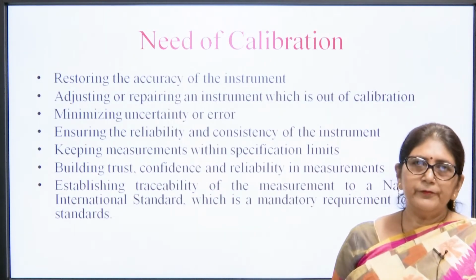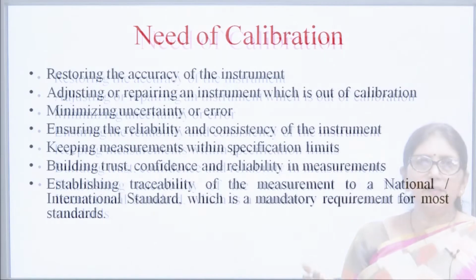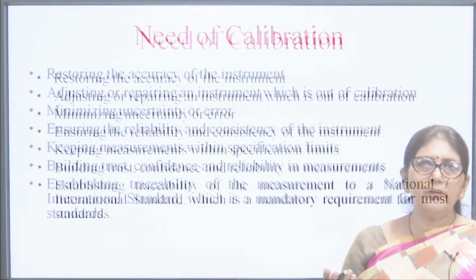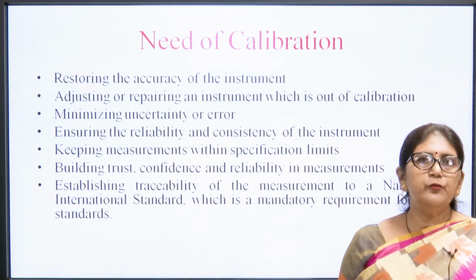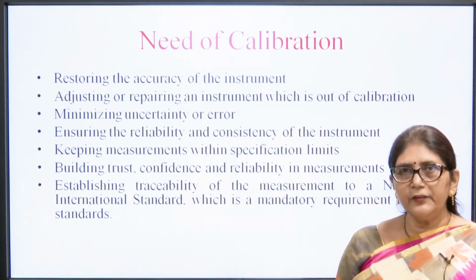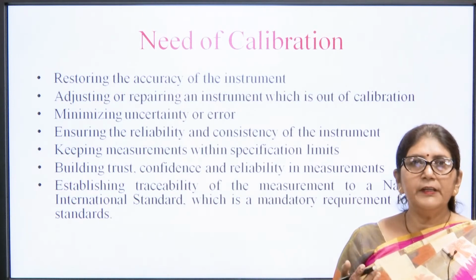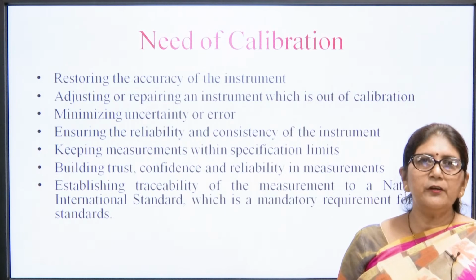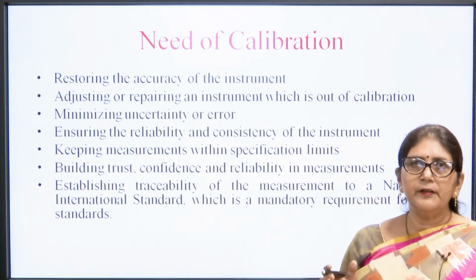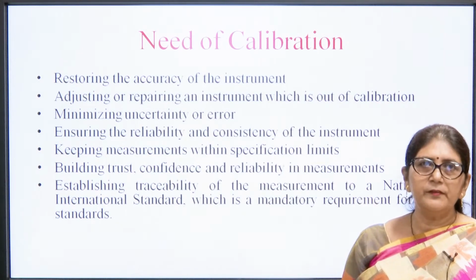So, what is the need of calibration? Restoring the accuracy of the instrument, adjusting or repairing the instrument which is out of calibration. We have to minimize the uncertainty of error, ensuring the reliability and consistency of the instrument and keeping our measurement within specification limits.